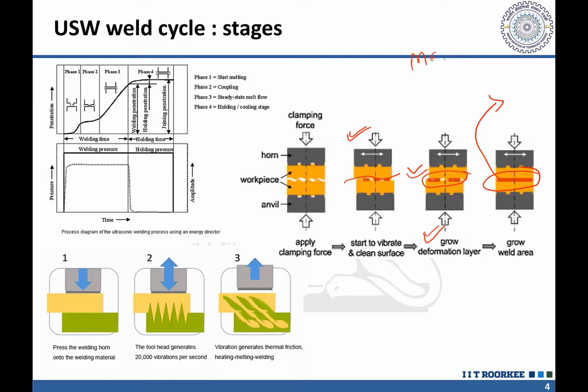As I said, there may be complete melting like in the polymeric materials, or there may be a significant rise in temperature, maybe 0.4 to say 0.6 times their melting point, which many times is high enough to facilitate recrystallization, to cause the development of the heat affected zone, recovery and recrystallization, even over tempering, over aging. So those things will also be affecting the mechanical properties depending upon the condition or the type of the metal.